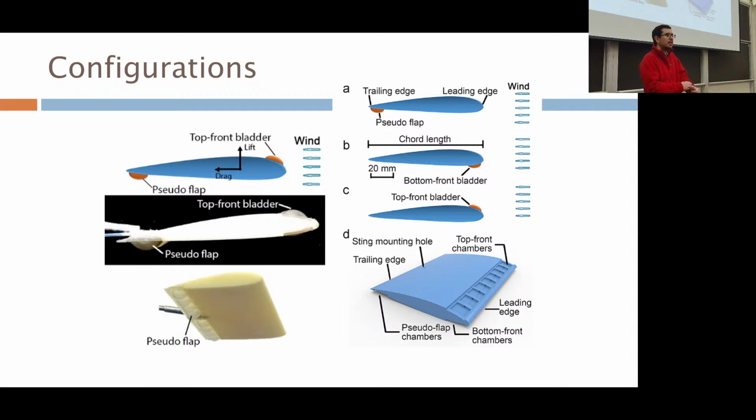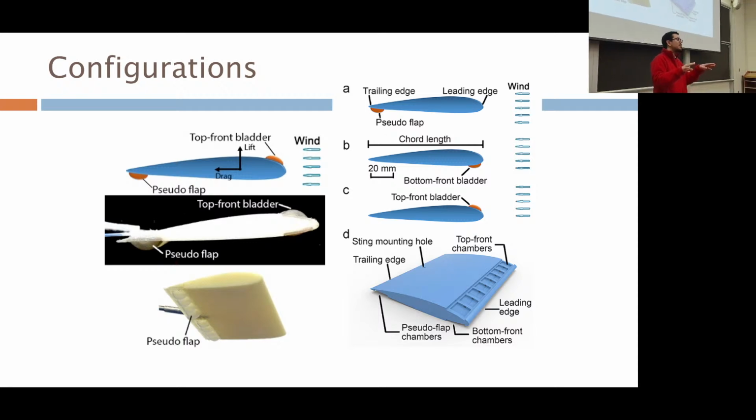You remember we talked briefly about symmetric and asymmetric airfoils? The asymmetric airfoils typically have some camber to them, right? So what does camber mean? That means they're kind of rounded. One of the interesting things about camber is it makes an airfoil at 0 angle of attack produce lift, because a symmetric airfoil at 0 angle of attack should not be producing any lift.